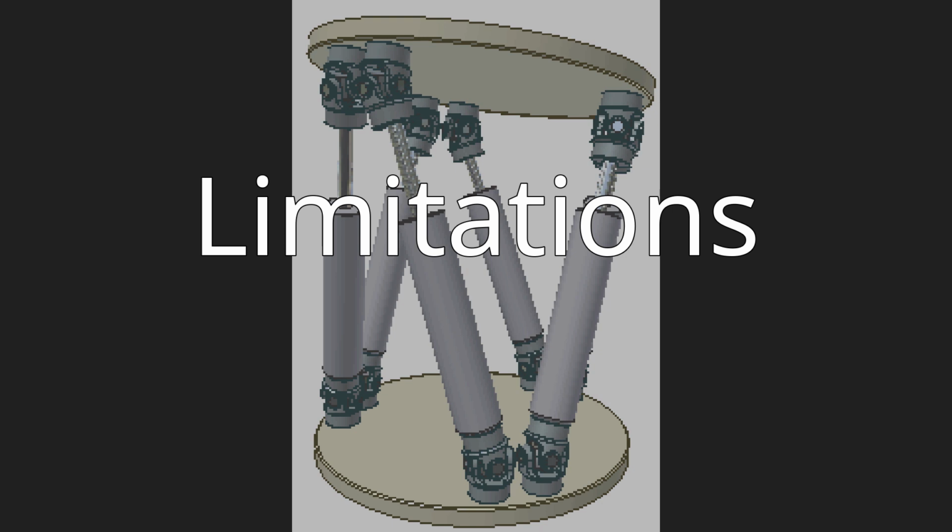Washout filters take advantage of the limitations of human sensing to give the appearance of a larger simulation environment than actually exists. For example, a pilot in a motion simulator may execute a maneuver. In this situation, a washout filter allows the system to slowly move back to an equilibrium position at a rate below the threshold which the pilot can detect. The benefit of this is that the motion system now has a greater range of motion available for when the pilot executes his next maneuver.